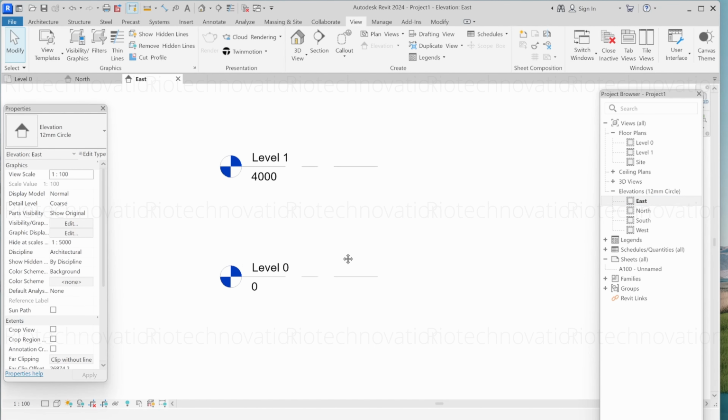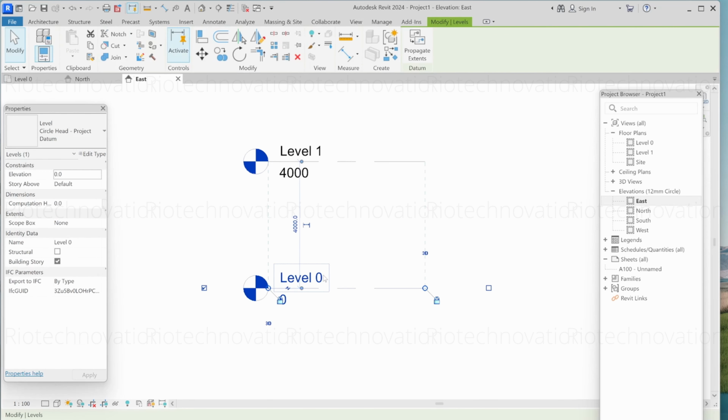Now you got this kind of interface. We will set from bottom to top. I have a bottom level which is already marked, set here at 0. I'll consider that as 0. Anything coming like a substructure, I'll mark with a minus. So this is my 0 level, which I will normally treat as ground surface. This is ground surface.